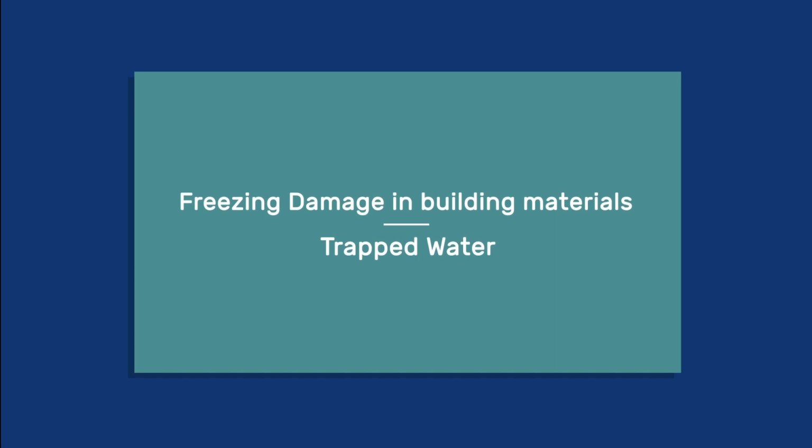In our introductory video on freezing damage in building materials, we saw one way in which freezing damage may develop in porous materials. This concerned the specific and extreme case whereby freezing proceeds from all sides, a situation we refer to as Case 1. We also saw how unsaturated pores may prevent water from being trapped and generating stresses as it crystallizes.